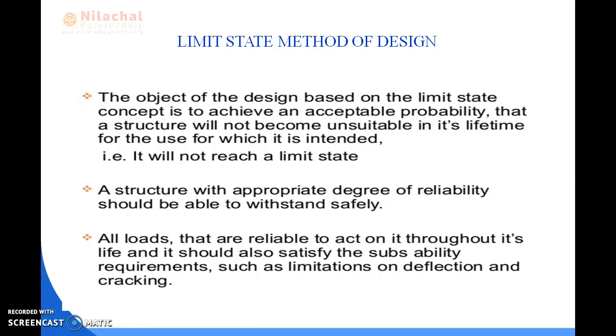In the limit state method of design, the object of the design based on the limit state concept is to achieve an acceptable probability that a structure will not become unsuitable in its lifetime for the use for which it is intended, that is, it will not reach a limit state.